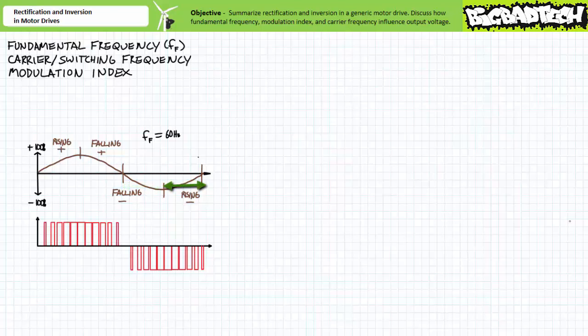Then it varies the duty cycle in a sinusoidal fashion from 100 back to 0% to generate the rising negative section over the remaining 4.2 milliseconds. In this graph, note I've drawn duty cycles sinusoidally alternating between positive 100% and negative 100%, which if you think about it is kind of nonsense, but it's my way of just reminding you that polarity is swapped for the negative half. Again, the details behind this simplification will make more sense when we examine PWM inverters in depth.